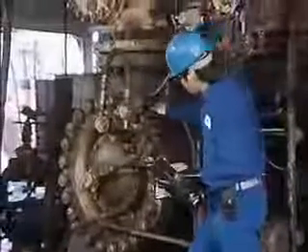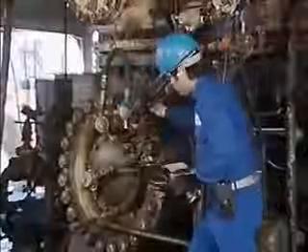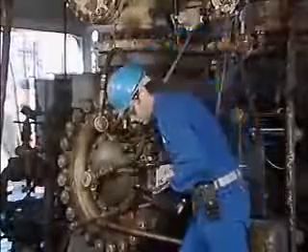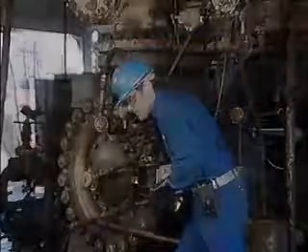Eventually, the compressor will be brought up to its minimum operating speed, which is the lowest speed the compressor can be operated at without causing surge or other operating problems. When the compressor reaches its minimum operating speed, the gas flow to the compressor can be started. Once the gas flow is started, the compressor can be brought up to operating speed at a rate prescribed by